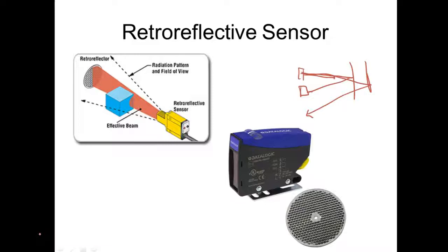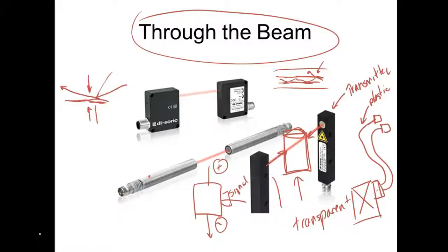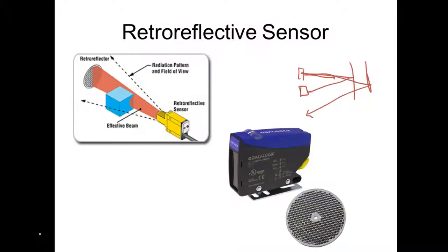Well, that's sort of true. The sensor that we got can be used for both a retroreflective and the next one we're looking at. Which one has the ability to have the longest sensing distance? Through-beam. Retroreflective has to bounce off. So that means the light has got to travel all the way out, hit the retroreflector, and do what? Come back. Through beam goes from transmitter to receiver.